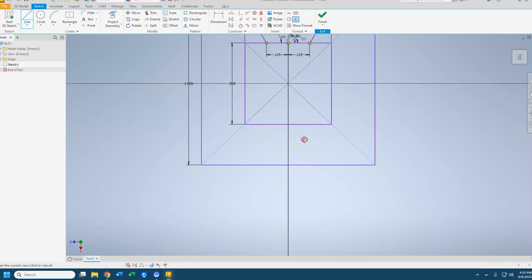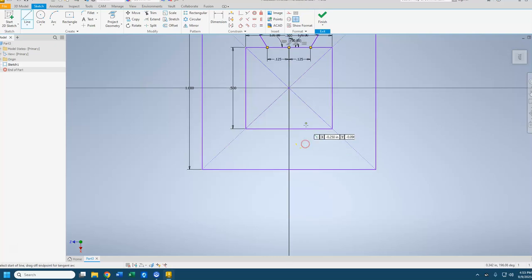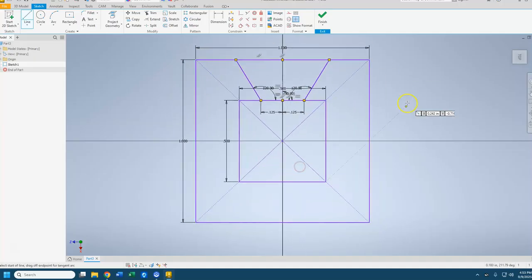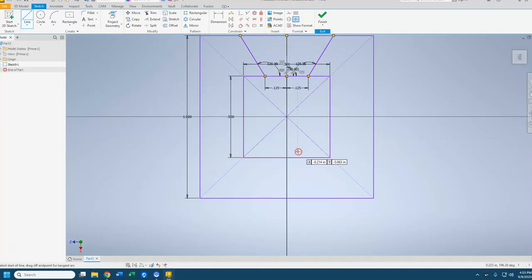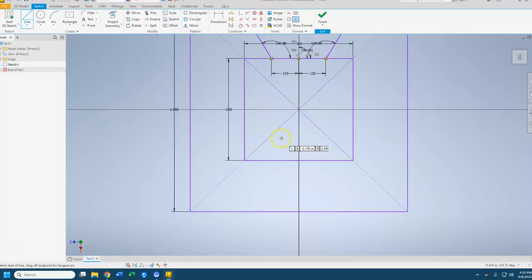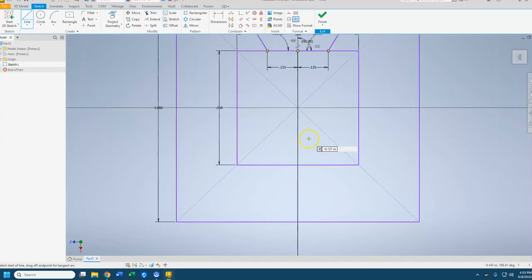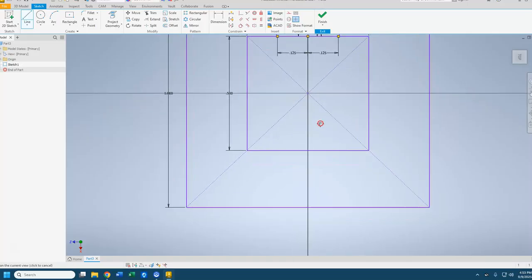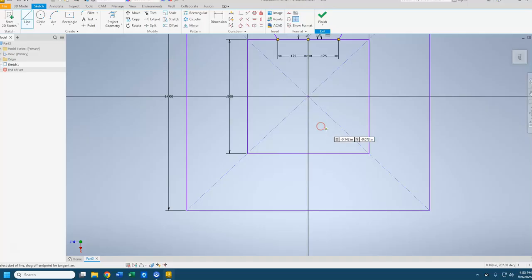What I just used, and you saw that hand show up, I'm panning the view. So I'm not moving anything within the drawing, but I'm moving where I'm viewing. And that's especially helpful if I have to zoom in to see anything. So to zoom, I'm using my scroll wheel like a scroll wheel. And to pan, I'm going to use my scroll wheel as a button. And that's going to allow me to move what I'm seeing on my screen. So I'm going to grab my line tool, start at the bottom of my half-inch square.